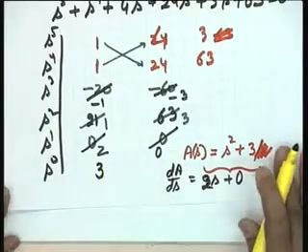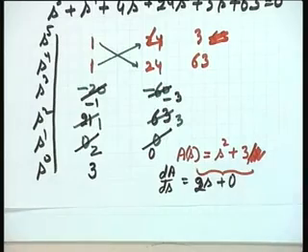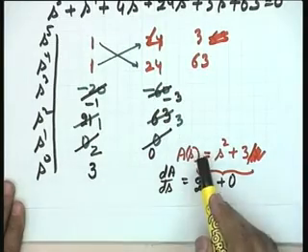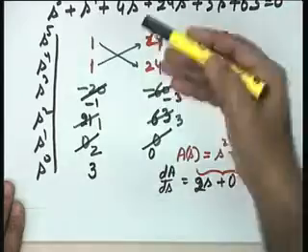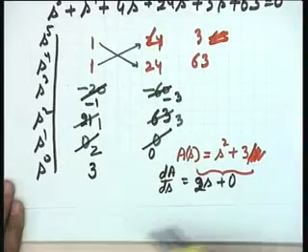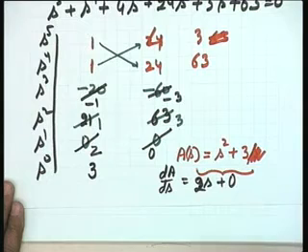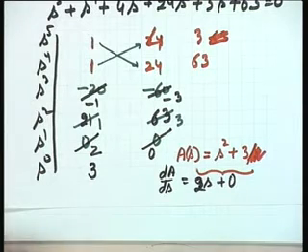In this case the completion is no problem at all, because this will now be 3 with the 0 and 0 replaced by 2 and 0. Now the problem of infinity is not occurring, and therefore you can write this coefficient as 3. Look at the first column, please. If you look at the first column, you find that there are 2 sign changes.